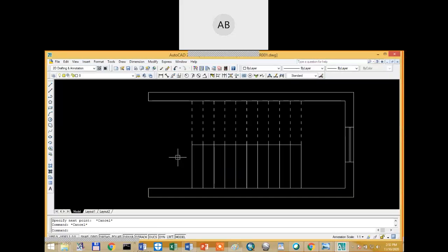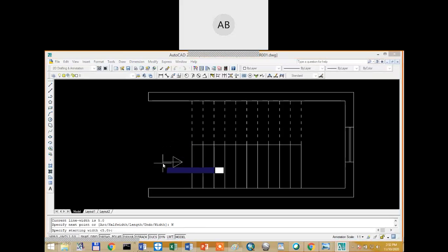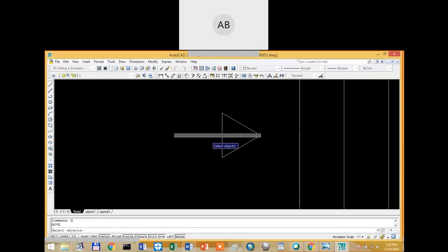So, remember the polygon command, P-O-L, polygon. So I type P-O-L, polygon, and then it asks the number of sides, I say it is 3. Why? Because I am going to draw a triangle. This is a triangle. Then I draw a polyline from here. I keep the width around 5 millimeter both sides. Width, suppose 10 millimeter, 20, okay. Why am I drawing this? Can you say?